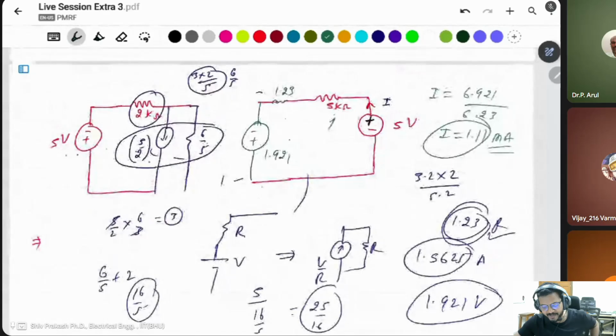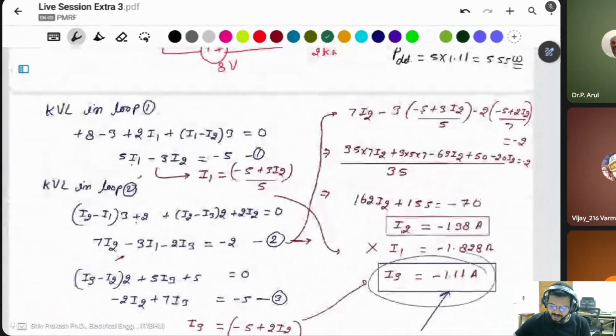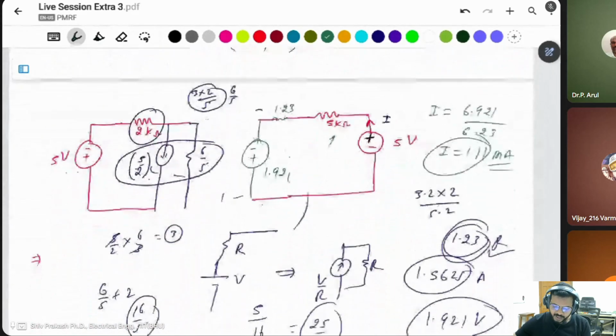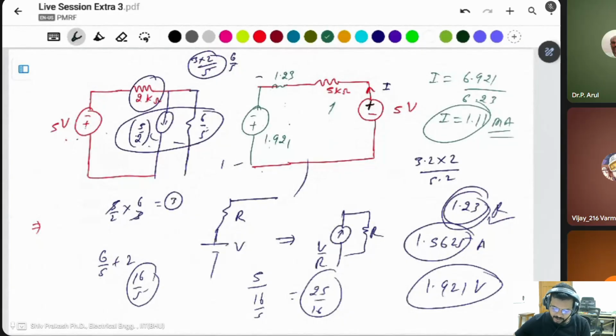But you have to check this forwardly. Change this one by using a calculator. Simply change voltage source to current source, then current source to voltage source, like that. All the calculation you can do on the calculator. That time this will be easy to solve. But in the previous method we were using KVL equations. In a physical calculator, equation mode is available, but in an online calculator there is no equation solving method. So source transformation is the better option for solving this problem.